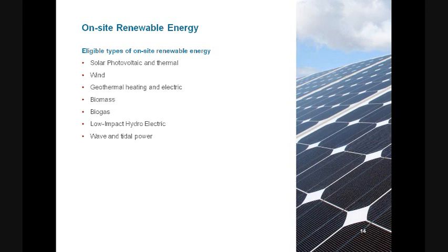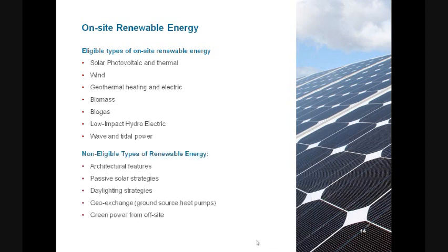Is that okay? Great. Okay, so if we're talking about on-site, these are the types of LEED eligible on-site renewable energy. Here are some examples of what's not eligible for LEED points. Things like passive solar strategies or daylighting strategies wouldn't apply to this particular credit. What we are talking about is on-site solar and geothermal and biomass and things of that nature.